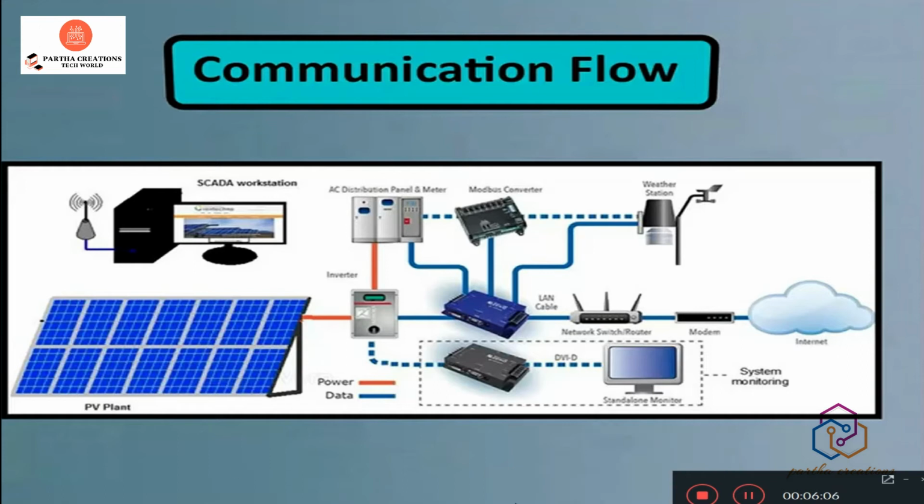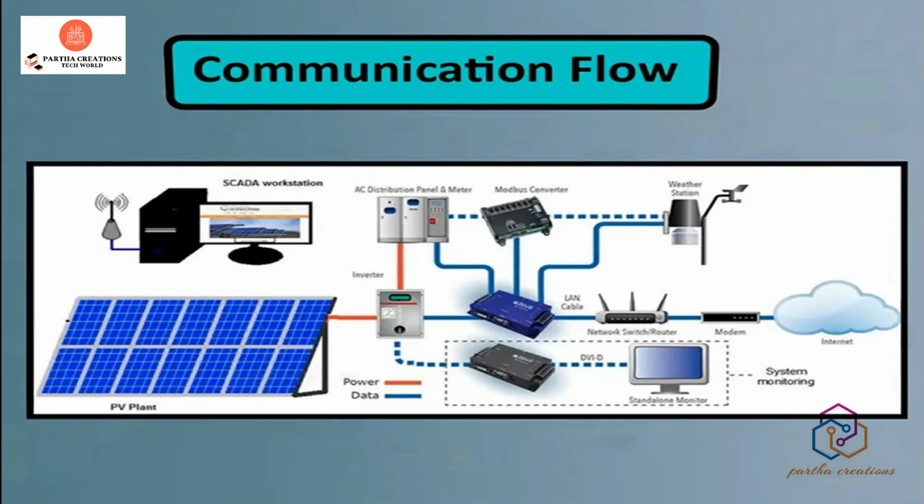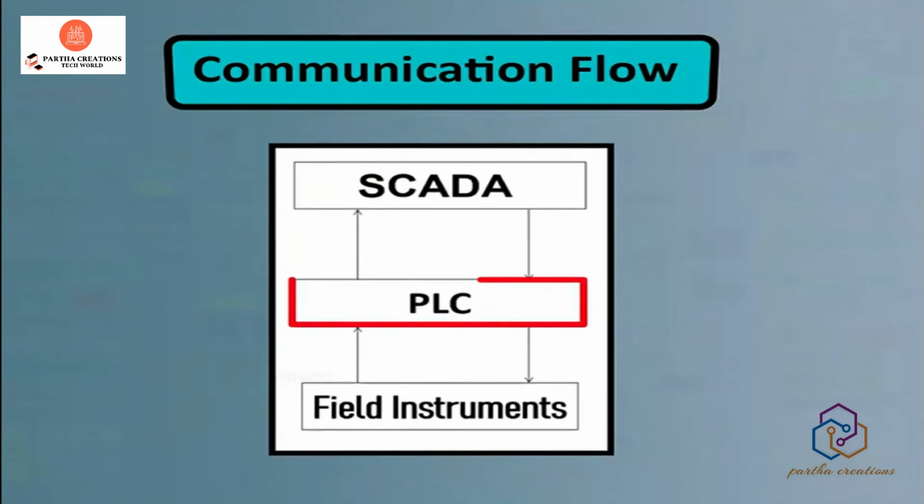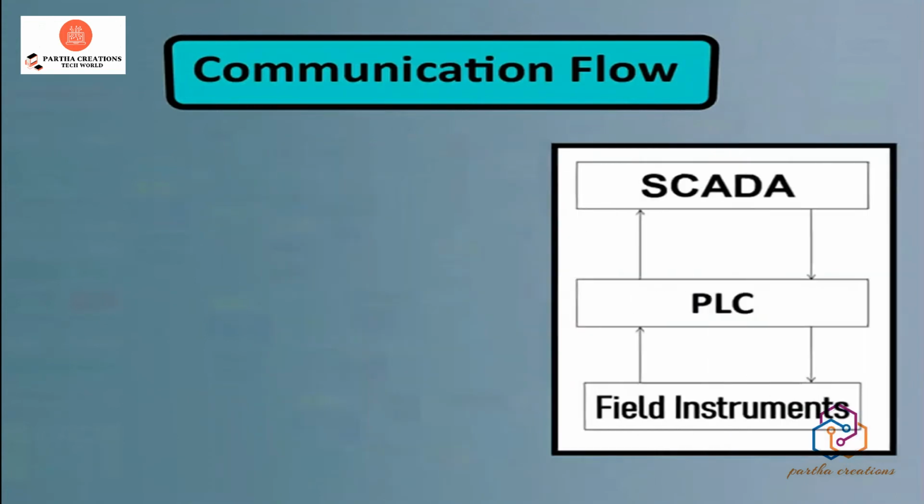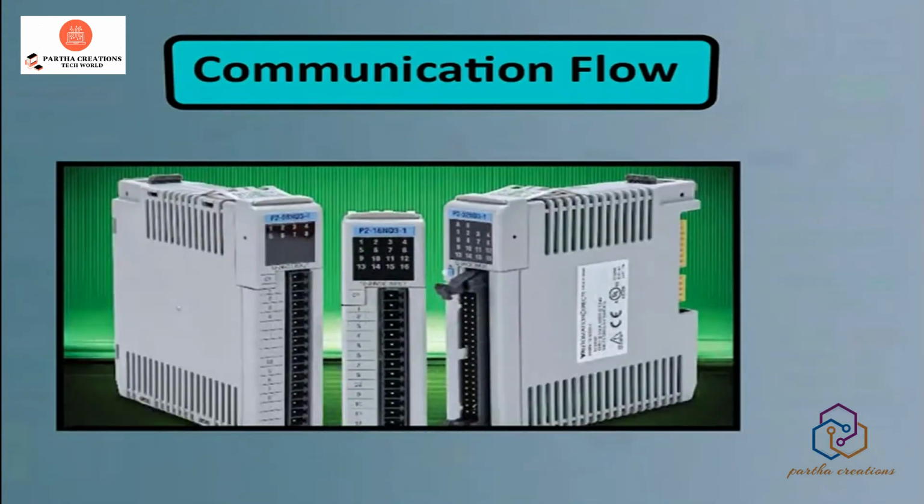where the processes are undergoing. Now, these sensors where the processes are running are known as field instruments. These field instruments sense the PV and provide us with the data. The data is then transferred as an input for the controller. The controller is the PLC which has been installed, and whatever data is being collected is being sent to the PLC. Okay? Now, in which form is the data being retrieved?